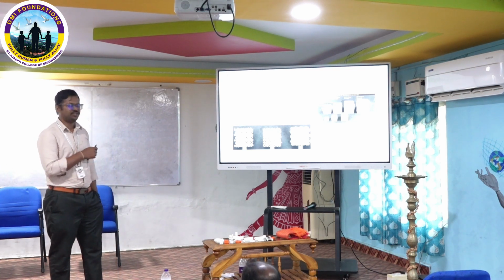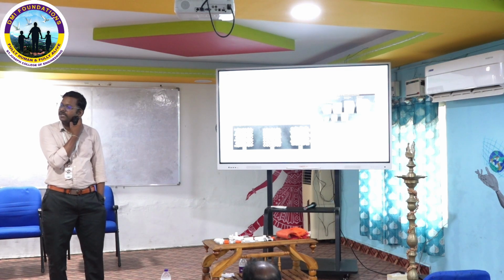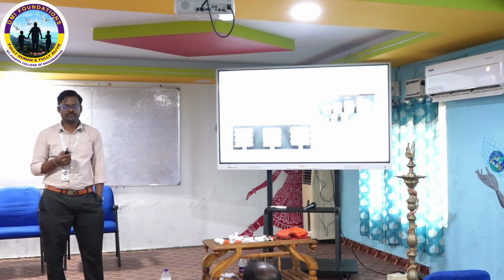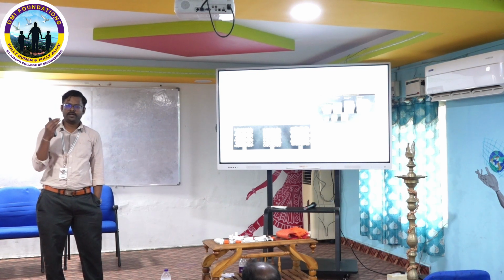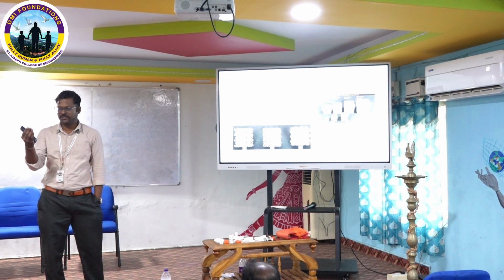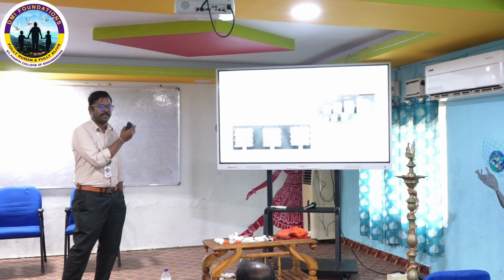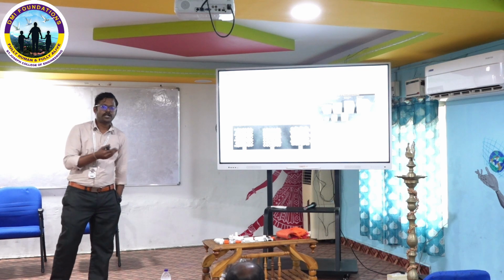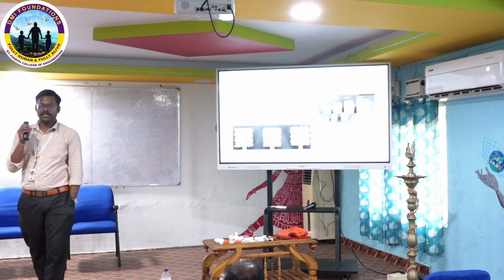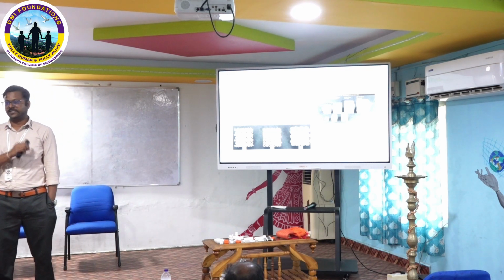Another thing is aspect ratio. Aspect ratio is nothing but the L by D ratio, that is, the length of the strut and the diameter of the strut. If we consider relative density, at the same time it should come out as an acceptable aspect ratio. Also we need to consider DFAM, design for additive manufacturing, here.